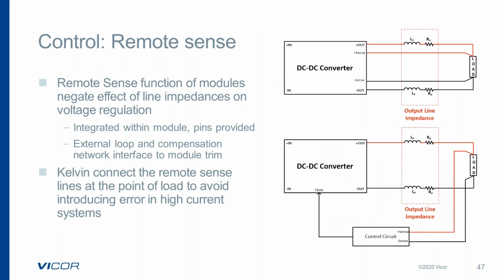So when we actually use those systems, we've got to make sure that those communication systems are tied to signal grounds or very low noise grounds, such that that communication isn't corrupted by switching noise.